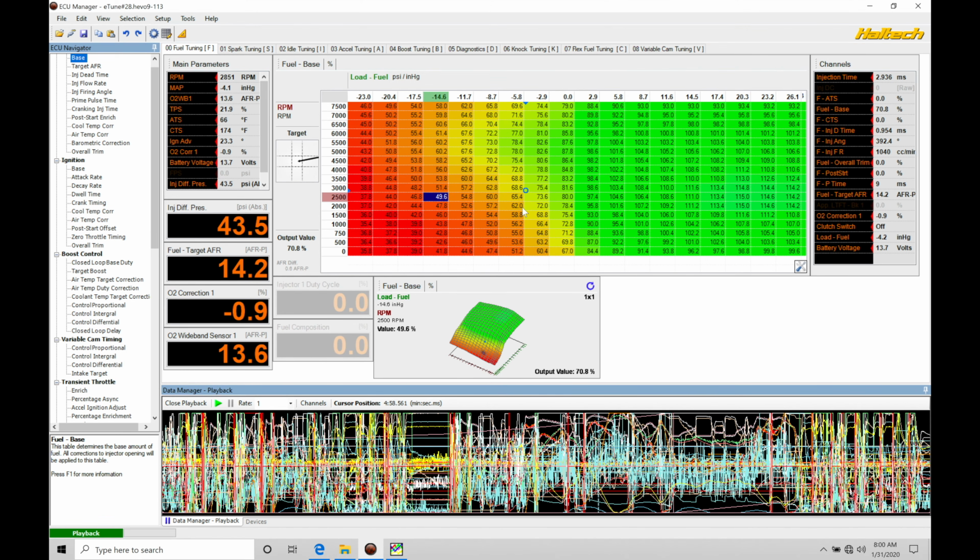So that's a little bit time consuming, especially if we're working with a data log that's 10 or 20 minutes long, even a data log that's several minutes long that can still take us double or triple the time to process this data that we've captured down here. There's a much more efficient way to do this, a much more precise way to do this, that we can dial in our main VE table within 1 or 2 revisions. I'm going to be showing you how to accomplish that.